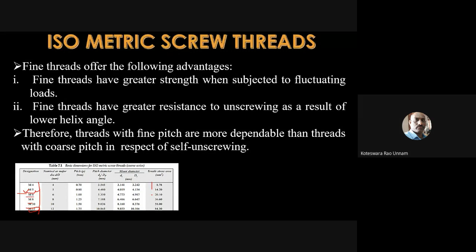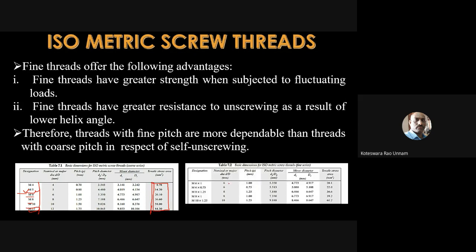Here in this column you have the corresponding tensile stress area also. Straight away from the data book you can pick that and find the tensile stress. Then in the second picture you can see that this is for the fine series.